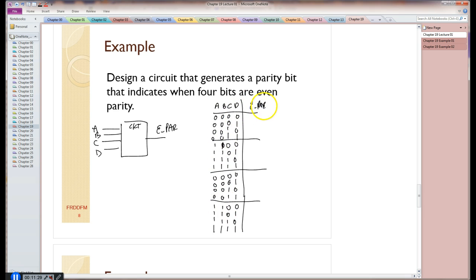So what this is saying is, is this 4 bits even parity? Yes, no, no, yes. Okay, even. There's 2 bits set. Yes, no, no, yes. Even parity. Yes, no, no, yes. Even parity. Yes, no, no, yes. Okay, so in the end, I'm not going to grind through these equations, but you can see these all happen to be XOR gates, individual XOR terms in here.